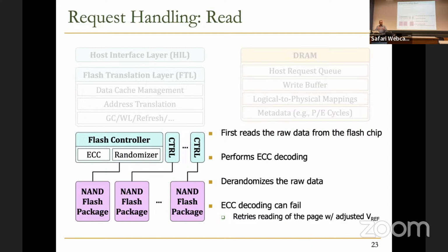We're going to learn about what the reference voltage is, but essentially we showed how PCM works, right? PCM was like the distribution of the resistance. And we showed that we can chop the distribution of the resistance in order to get what data has been stored. So in flash memory also, you have a distribution of threshold voltage, and you can chop that window into several domains or several margins. Essentially, you apply a reference voltage, and with that reference voltage, you can decide if your data is 0 or 1 or whatever.